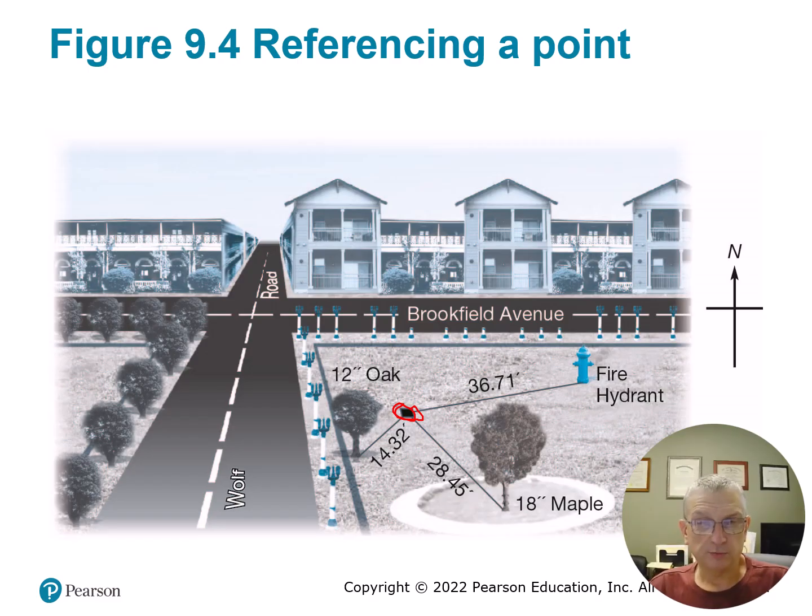Now, part of the reason that this is still in textbooks is it's very common practice in the southeast that traversing is done using magnetic nails. For example, I use 6-inch long magnetized nails with a nice divot and a square on the top of it for rods to set in, for instruments to be able to be set up precisely over, and they are easily found with a metal detector.